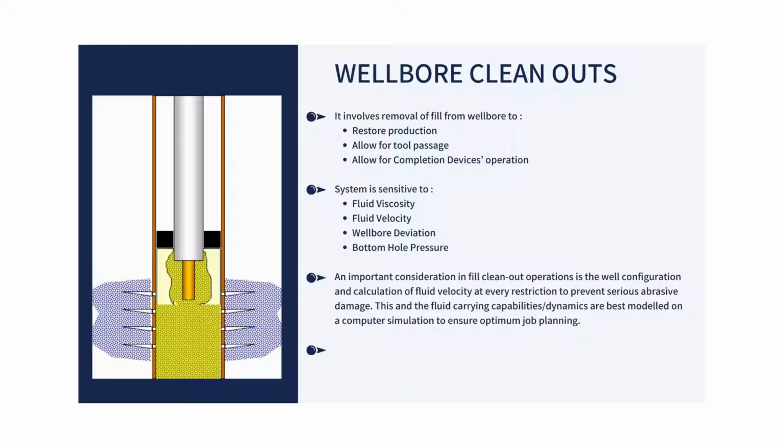An important consideration in fill cleanout operations is the well configuration and calculation of fluid velocity at every restriction to prevent serious abrasive damage. This and the fluid carrying capabilities and dynamics are best modeled on a computer simulation to ensure optimum job planning. In broad terms, cleanouts are divided into two categories: removing solids, such as formation sand and frac sand, and removing sludge.